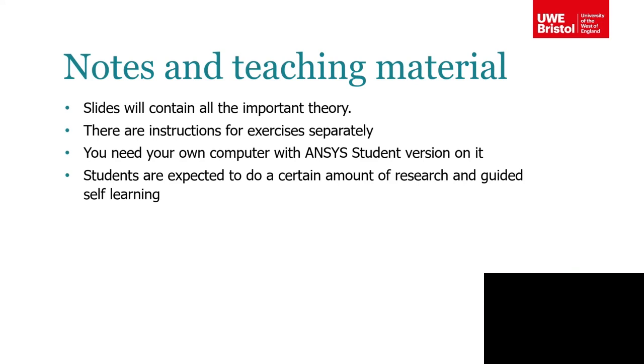The student version has a limit to the element count that you can use. For FEA that is not bad, but for CFD you get over the limit really quickly, even in the simplest of parts. And it's only a limit on the mesh. The software is the same, so it takes the same space on your computer. If the mesh is bad, then the results are wrong. You need 32 gigs to install; 16 is the software space. Heavy on your computer.